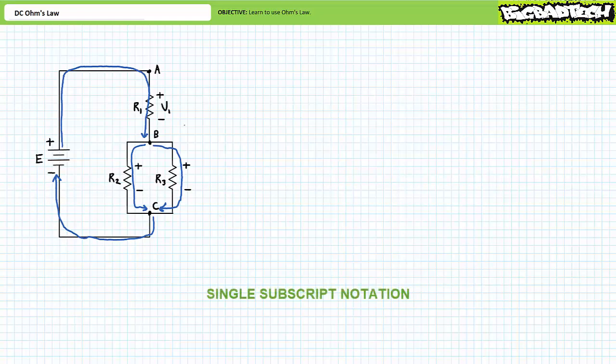Using single subscript notation, the voltage drop across R1 could be designated as V1, the voltage drop across resistor 2 designated as V2, and the voltage drop across resistor 3 designated as V3. If, however, we chose to use double subscript notation, the voltage drop across resistor R1 could be designated as VAB. The voltage drop across resistor R2 could be designated as VBC, and the voltage drop across resistor R3 could also